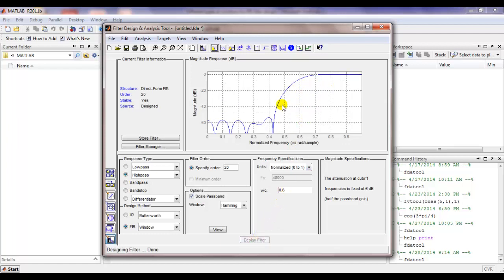And you see that now the shape looks very different. I have about this -53 dBs around here. But look at this, this number has really gone down. It was -21 dBs, it was here. And that's why this looks almost flat, because the ripples in the passband are now, instead of -21 dB, they are -53 dB. So it almost looks flat to you. But look at the transition width. It has expanded.